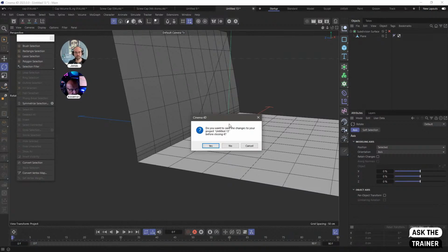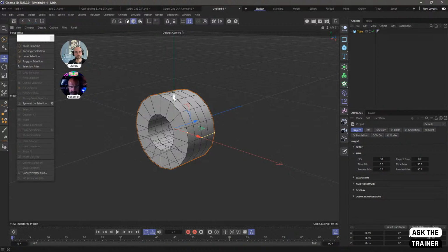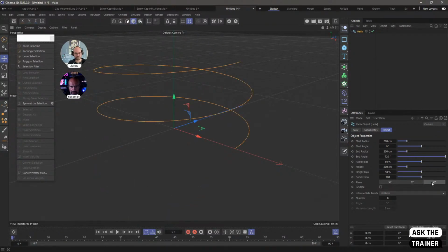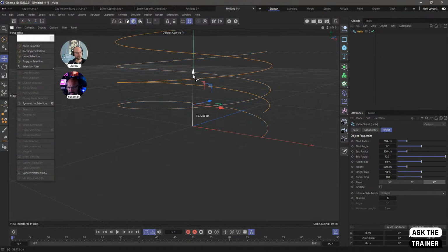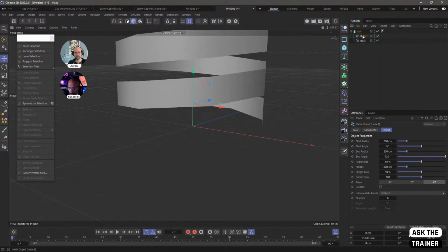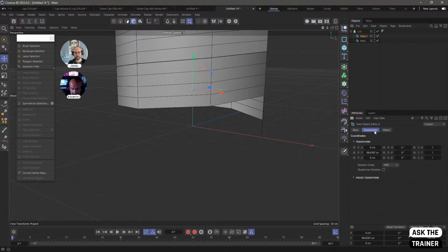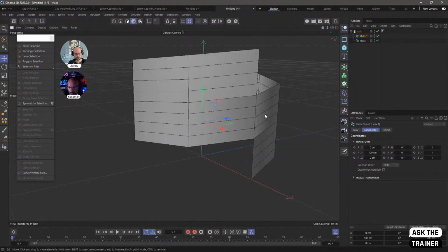And now very quickly, what is it, 30? Right, I'll do this in 5 minutes or less. New file. Let's create a screw cap. Let me show you some magical techniques I've developed over the years. Make a copy of a helix. And let's go and add a loft and put them under the loft. Now, I'm going to raise this after I've added these. I'm going to raise this up approximately there. I'm going to find which number it is. It's 100. There we go. So that's a relatively good configuration for what I want to do.